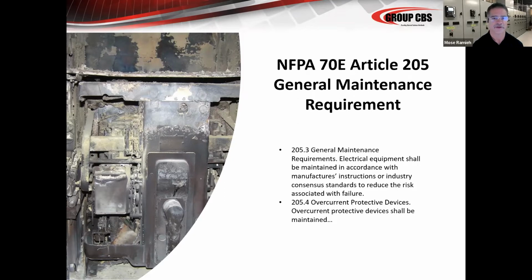And in a nutshell, and I'll probably say this again as I go through this presentation, if your overcurrent devices are not operating properly, not set to your coordination and arc flash study, then the arc flash hazard that the individual will be subjected to could be much higher than the study and the label on the equipment would otherwise say. So it's important that we periodically check our equipment to make sure it's operating properly.